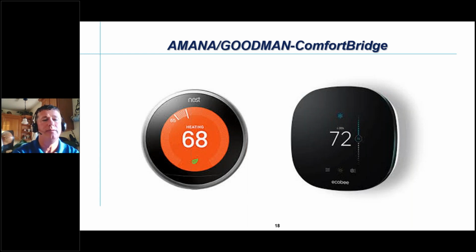They took all of the modulating algorithms that would have been in the thermostat and put them back in the equipment. So now all the equipment needs is a switch for am I hot or a switch for am I cold? And then it lets the equipment use its own algorithms to modulate how much of a demand on the equipment it actually needs. And it was a game changer.